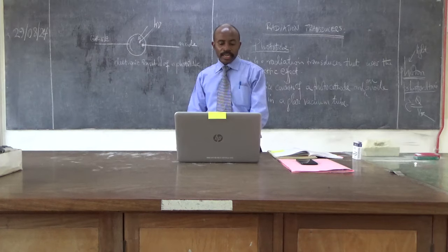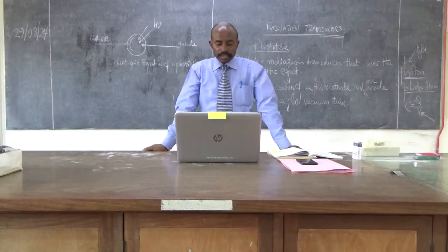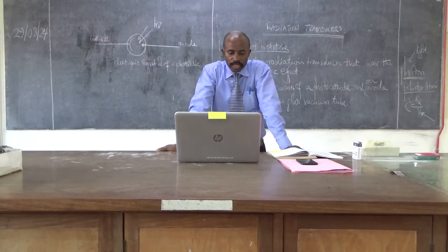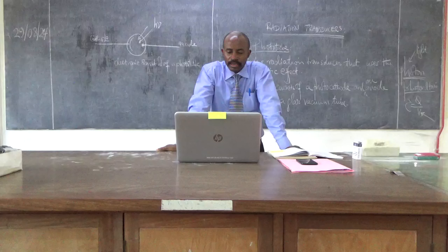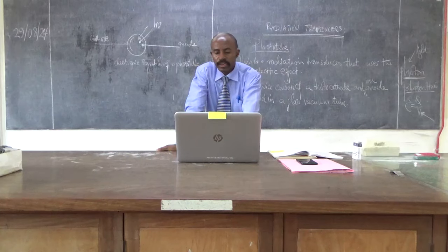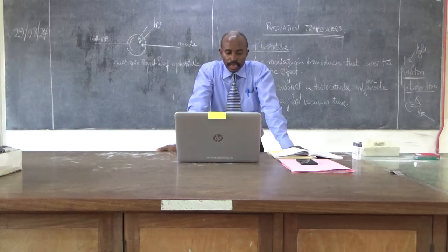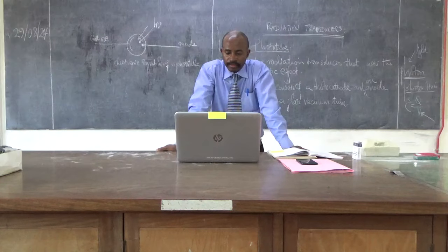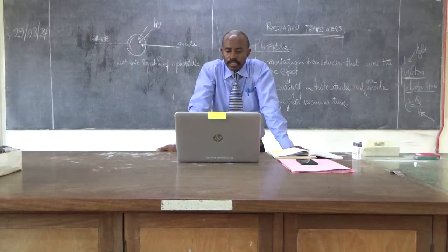So light is striking a large photocathode surface, and transfers energy to the electrons in the metal, causing them to be ejected. They are then attracted by the anode, which is held at a voltage that is positive with respect to the cathode. The resultant current is directly related to the number of photons, or intensity of the light, that was striking the cathode surface, and the ease with which electrons are ejected from the surface is related to the property of the metal known as its work function.